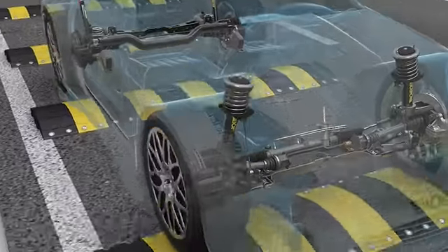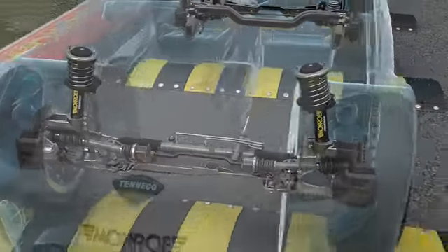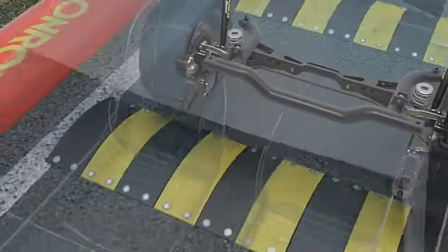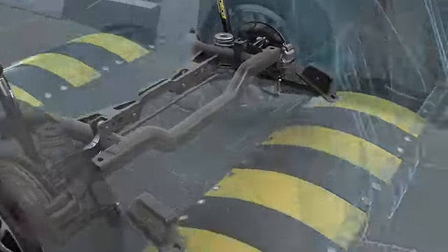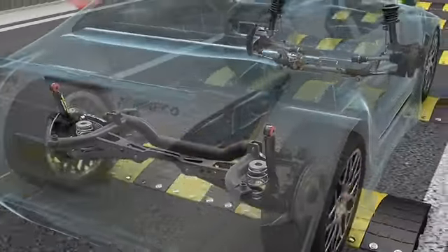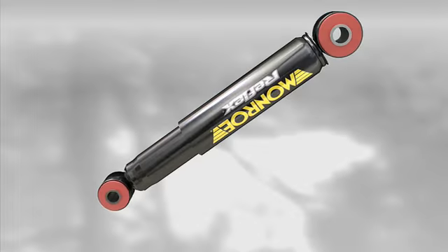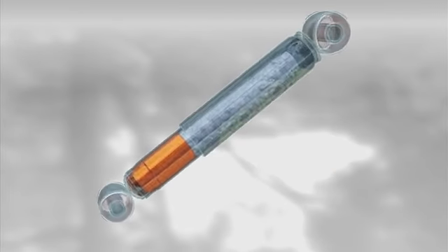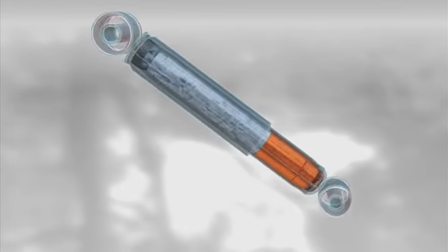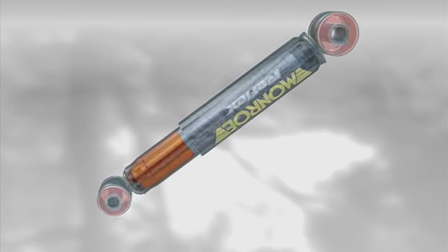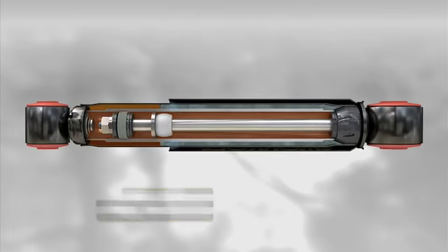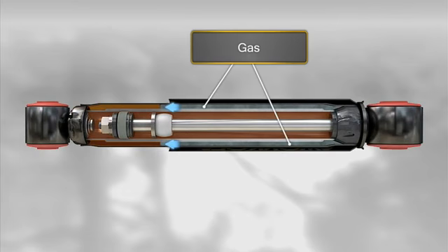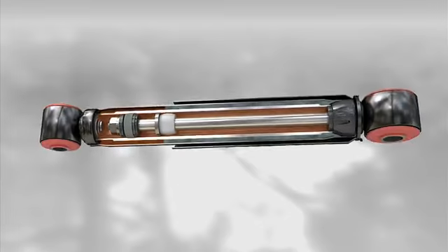In the case of the gas twin-tube shock absorber, the low-pressure compressed nitrogen gas prevents the formation of air bubbles, which produce the aeration problem and also their negative consequences for vehicle safety. Gas-charged shock absorbers offer other significant advantages over hydraulic oil shock absorbers. The pressurized gas in the reserve chamber pushes the oil into the working chamber, keeping it constantly full. This effect eliminates the need to prime the shock absorber before fitting.